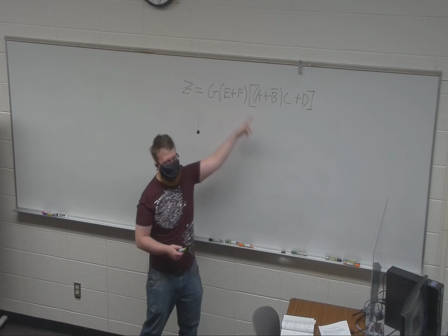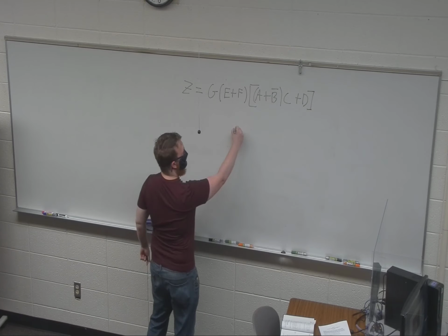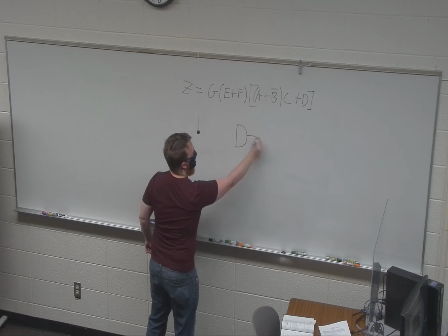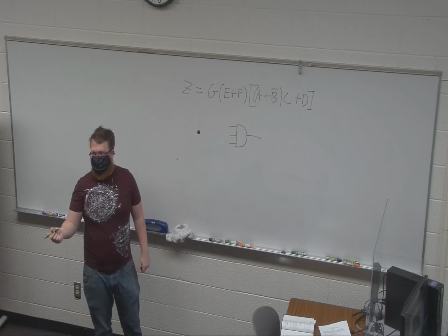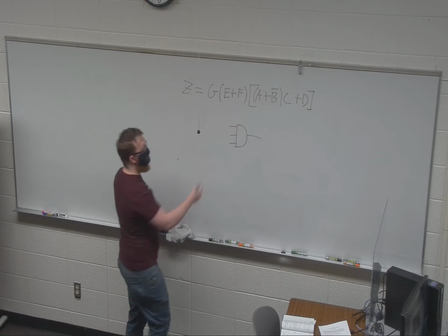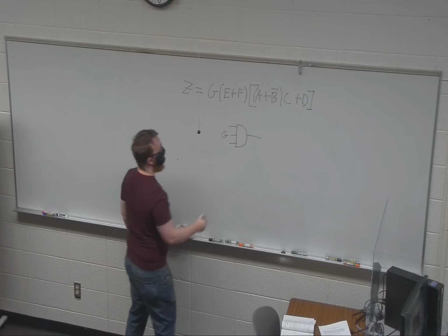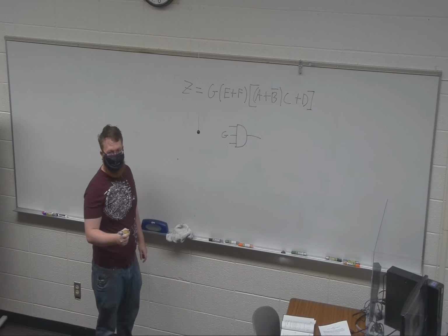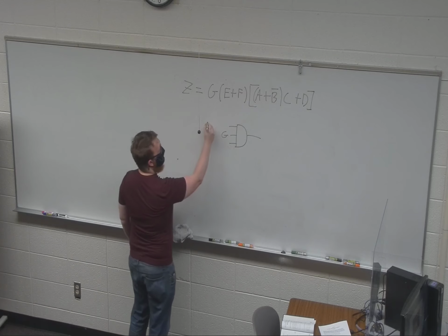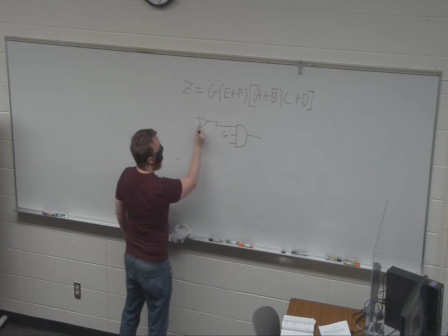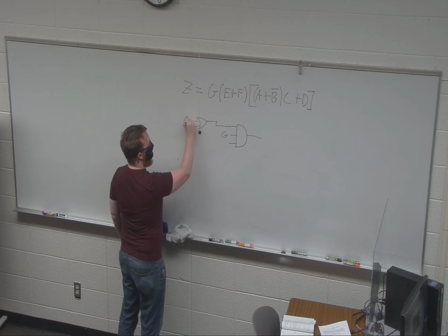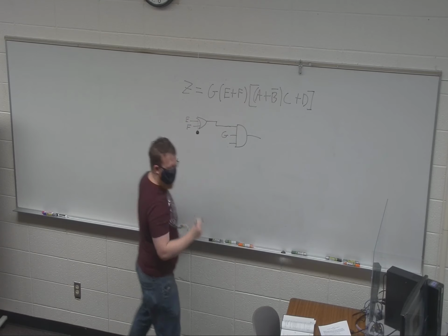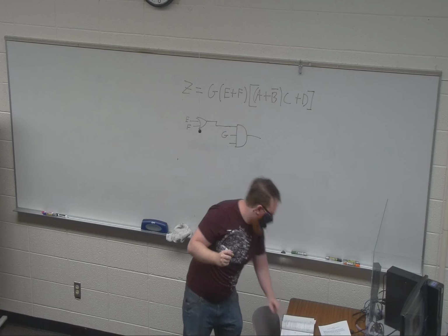An AND, right? We've got 3 AND terms. One of them is really easy. Which one's the easiest one? G. So I'm going to throw that in the middle. The next term? Yeah, so you're going to have an OR gate that's going into that. And it's going to be this pretty simple E OR F. Let me make sure I don't have any inversions. Okay.